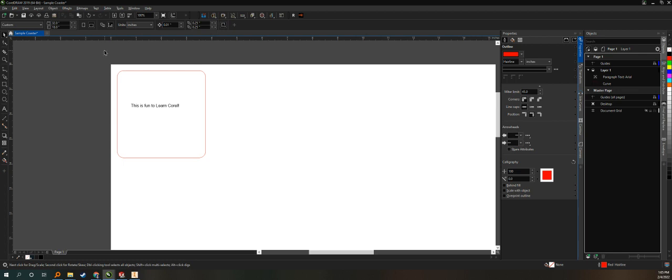So those three colors are what you're going to be using: red, blue, black. Black is any thickness, red is a through cut, and blue is a vector etch along the very top. In the next video, I'll be showing you how to put a picture on a coaster and engrave that.